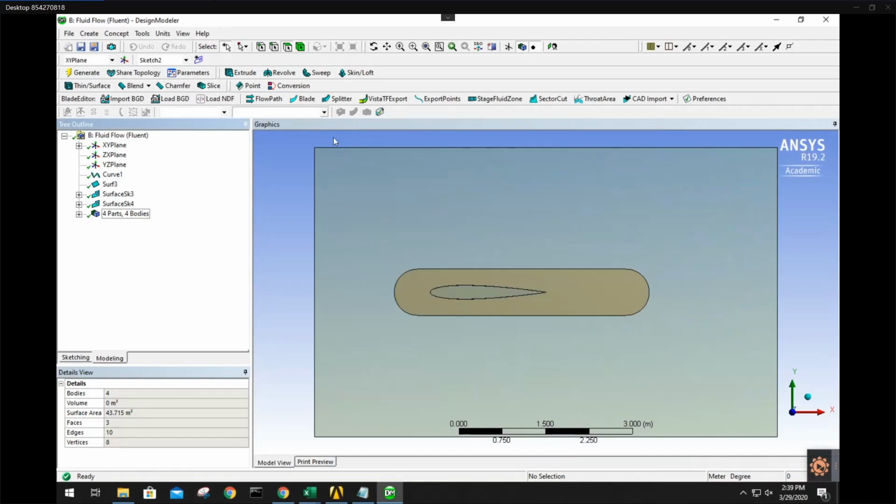So here it works. In this case, I didn't even use CMesh, because I'm going to limit myself on how much angle of attack I use. In real-world wind tunnels, you're not varying this inlet. In reality, you keep this constant and you vary the angle of attack of your airfoil, such that it rotates about this point clockwise, something like that. In reality these are walls. I could do walls, but I'm just going to set all of these to inlets.